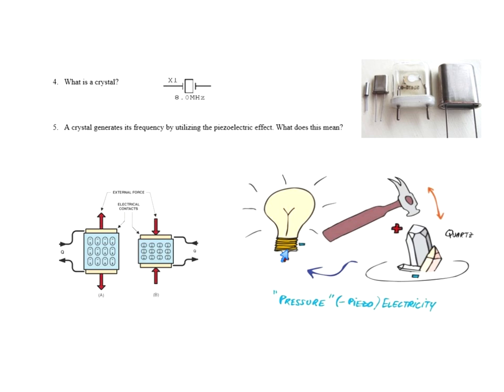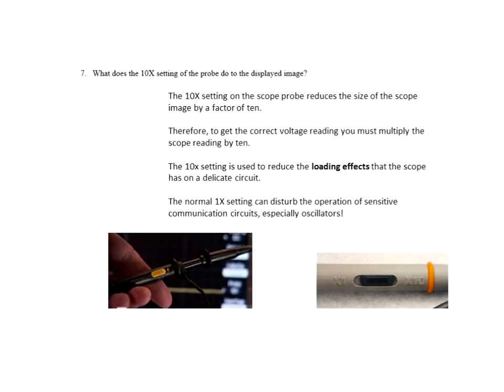Here's what ends up happening. When I apply a voltage to this terminal here on the crystal, I can make this crystal twist. When I release the voltage from that crystal, it'll twist back and release the voltage back into the circuit. So that's what we mean by the piezoelectric effect. It's typically experienced with quartz crystals. I think the question that you'll see will be something like, the effect that a quartz crystal utilizes to generate a frequency is the, and then you'll have to answer piezoelectric effect. It'll be something like that.